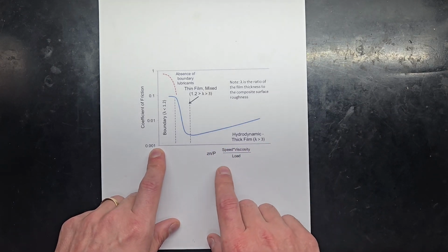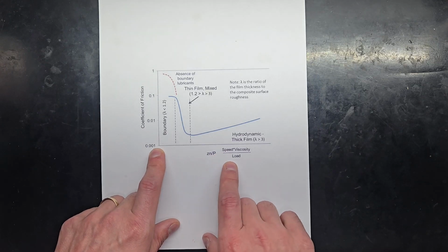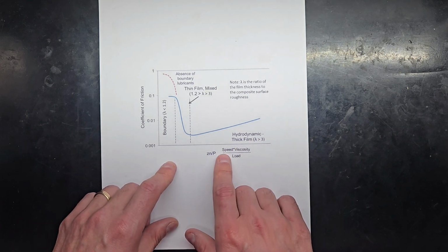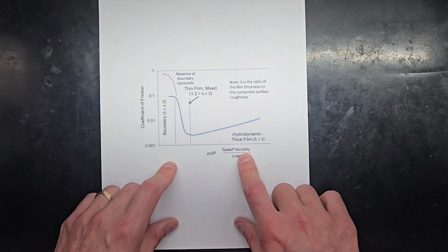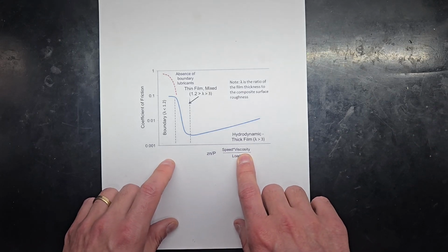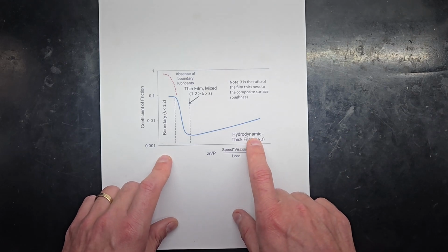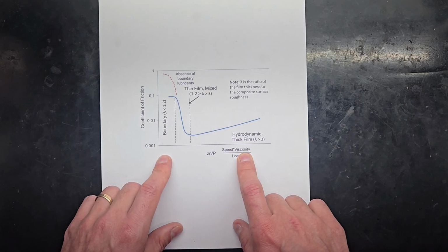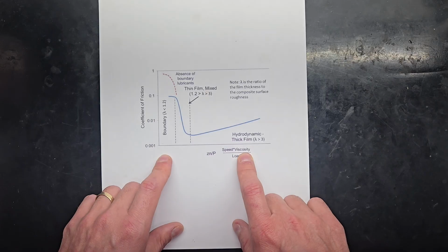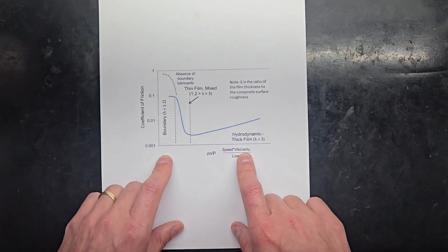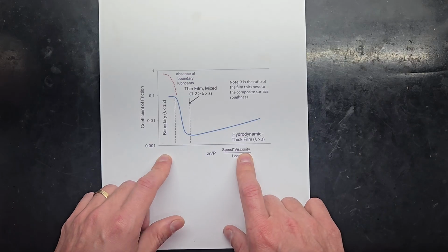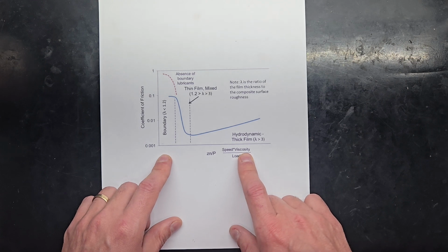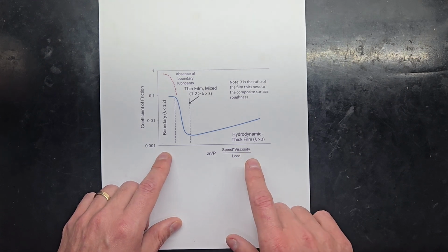In our firearms, we're not doing much for speed or load. We can tweak it a little bit with springs and powder charges, but for the most part, we're not doing that. The biggest knob as a consumer to help ensure we're in hydrodynamic lubrication is understanding the viscosity of the lubricants that we're using. So for me, I started this hunt and I'm still going down it, but I want to find partially the highest viscosity lubricant that still gets me the performance that I need.